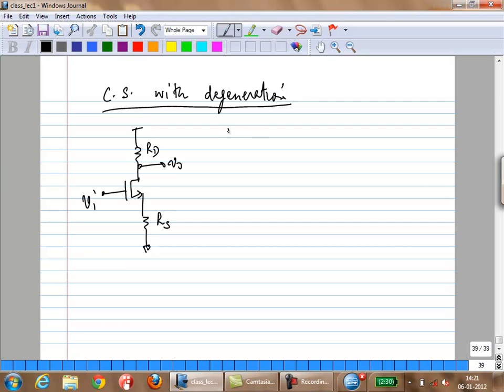Okay, so let's say you want to find out the gain of this. One way to do this is to split it up into two components. Remember, I talked about voltages getting converted to currents, getting multiplied by impedance to convert to voltage. So that is a good way to analyze even this circuit. You can split it up into an effective transconductance and the output impedance.